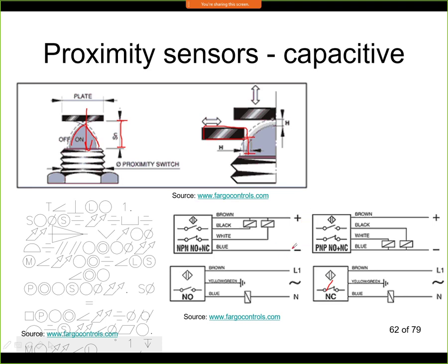In terms of safety, it is better to have the DC voltage 24 volts, for example, because if then someone will touch for some reason your outputs or your power supply voltage, then this low voltage DC is not dangerous at all. If you use this AC voltage, it's definitely more dangerous. But on the other hand, here with the AC version, you actually save for the power supply, so you don't have such a complicated connection because you are powering the sensors directly from the power network.